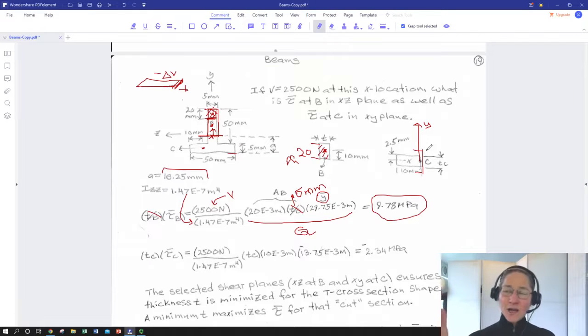So here we're going to be relying on the fact that whatever shear force is connecting this section here to the rest of the T down on the flange is going to be equal to something going on the face. So we're not slicing it all the way across the flange. We're just making a cut right through that minimum thickness at C. So I'm going to draw its thickness like that at C. Okay, so TC, thickness at C.